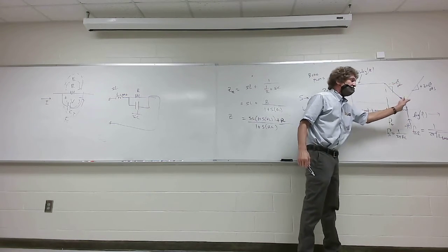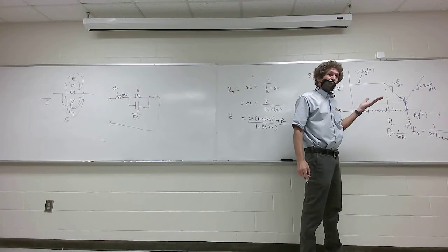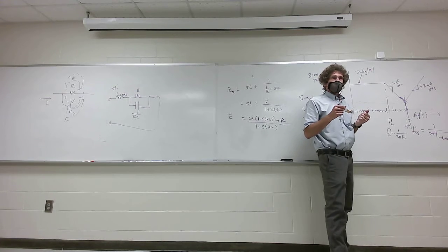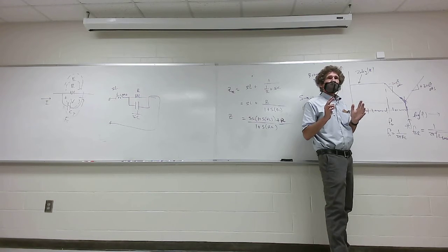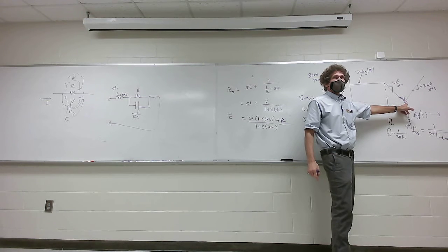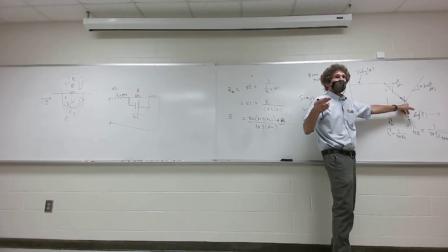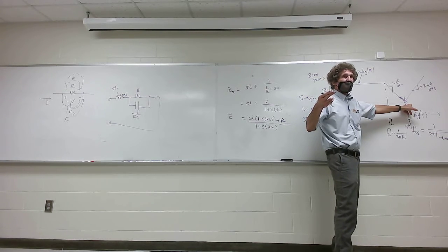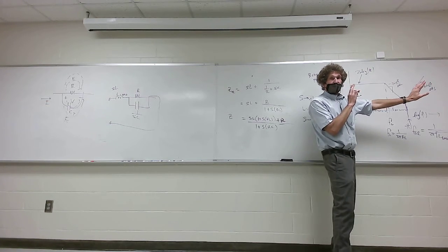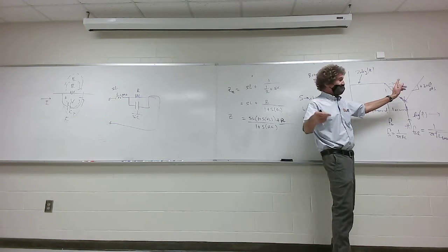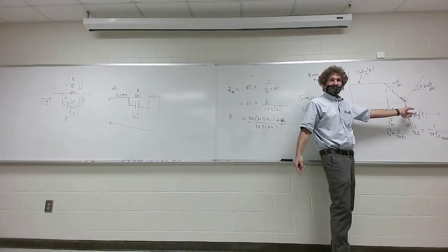This between here and here is where the critical drop occurs, you might say. And the rule of thumb, he has something about this in his book. I'm going to level with you. I'm not absolutely certain this is true in every case, but usually you want the self-resonance frequency to be 10 times higher than the highest frequency you'd be concerned about. You don't want to be close to it. Factor of 10 is usually a good standard way to keep away from things. Because the minute you start getting close to this, the value of the impedance that you were expecting could be anywhere on this line, and you don't want that.